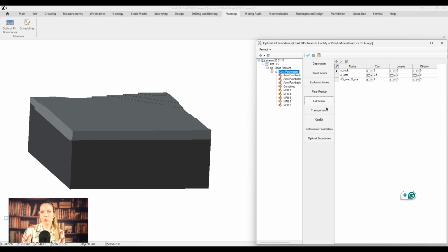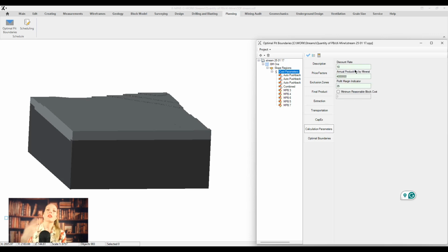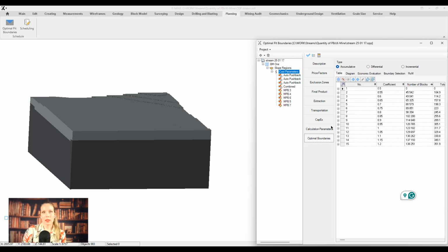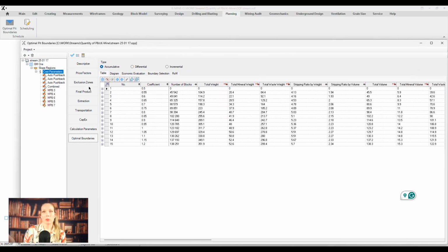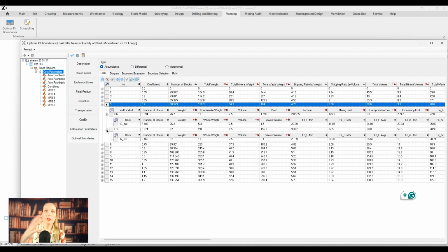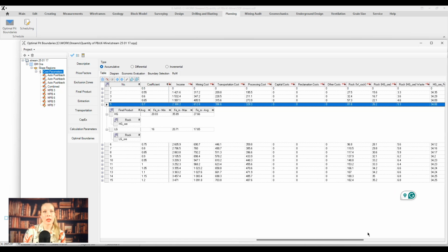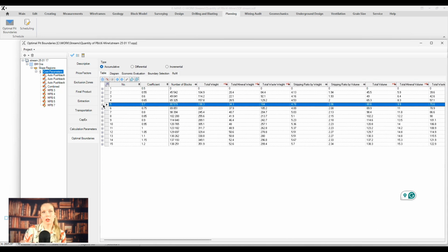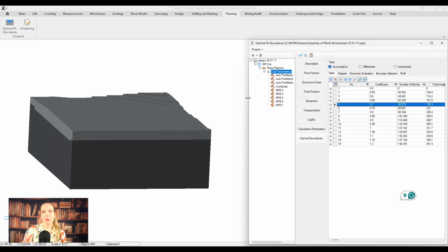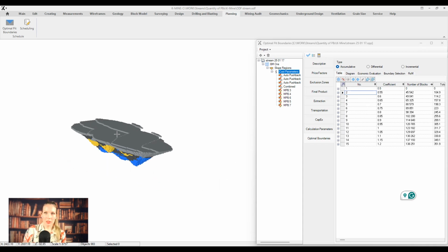For example, let's say we've made a project where we plugged in all various data like cut-off grade, extraction rates, how stable the pit is, and the mining costs. After doing the math, we get a set of final contours adjusted by what we call the price adjustment coefficient. The report is pretty thorough, painting a near real picture of mining operations with plenty of indicators and graphs for a first look. Each set of these block results can be viewed on its own, allowing you to explore how volumes grow as the product price goes up. This helps in deciding the pushback development sequence, aiming to maximize NPV.